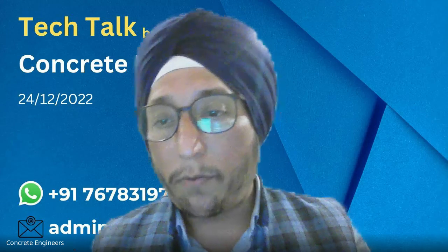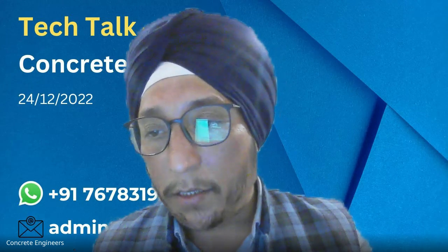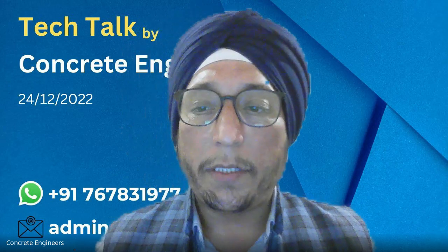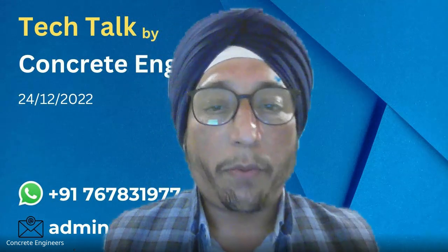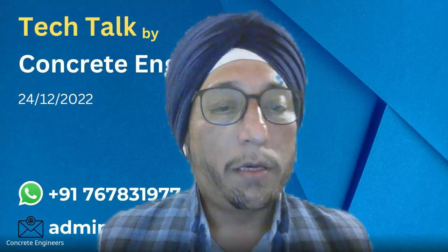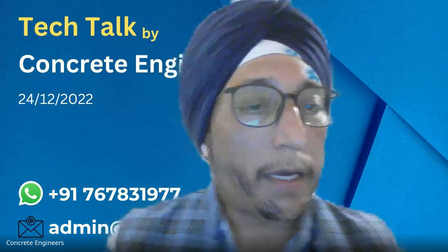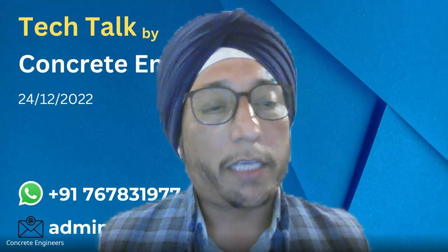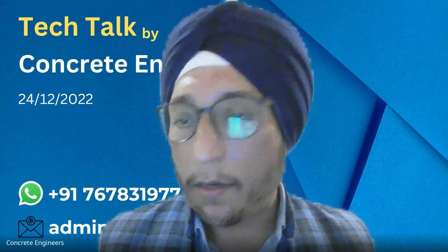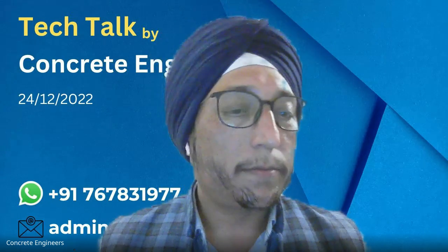And one question is from Mr. Deepak Sharma. Sir, how can concrete be saved at site because the recipe is not in our control? Probably he's talking about admixture recipe. Deepak ji, if you are there, you can elaborate your question. Sir, same problem: if we check slump at our batching plant, it is good, 170-180, and after going to site our concrete collapses to 200-210.